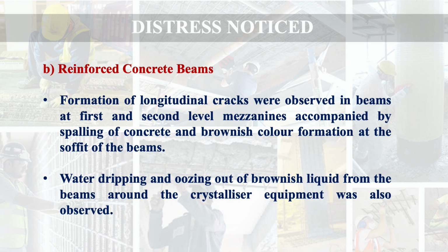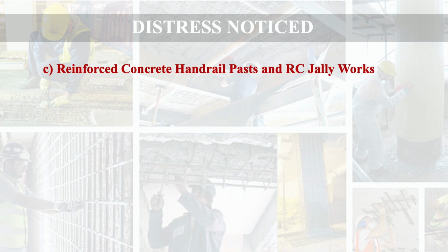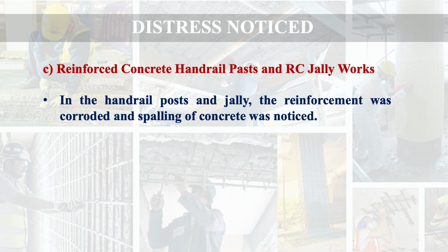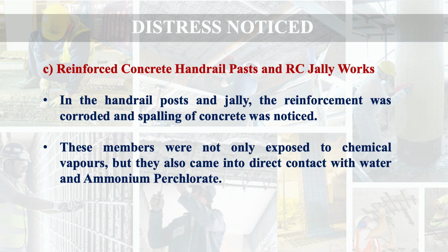Water dripping and oozing out of brownish liquid from the beam around the crystallizer equipment was also observed. Then what was observed in reinforced concrete handrail posts and RC jali works? In the handrail posts and jali, the reinforcement was corroded and spalling of concrete was noticed. These members were not only exposed to chemical vapors, but they also came into direct contact with water and ammonium perchlorate.